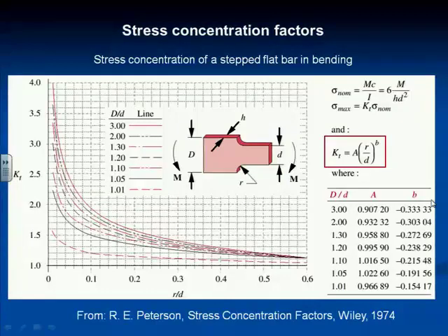Yes, sir. So there's a stress concentration at the radius? Yes. Sharp corners are your enemy in this business. So you don't want sharp corners because the radius is 0. So if that was a 90-degree turn rather than a radius, it would go to infinity. Like your hole, when you get that ellipse down to a crack, so that the vertical dimension is 0 and the horizontal is something, it's a crack. And that theoretical stress concentration goes to infinity. And the same is potentially true here.